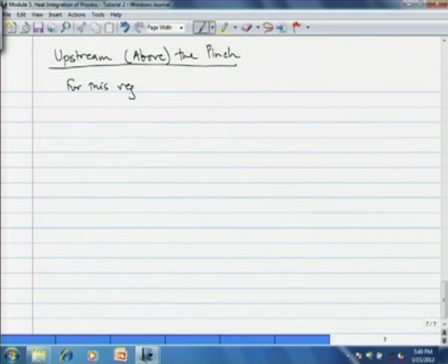In addition, for the above pinch region, we have some constraints as we have seen in the theory lecture. The constraints are: Cph has to be lesser than or equal to Cpc, and the number of hot streams has to be lesser than or equal to the number of cold streams. Now, let us see the heat surplus and heat requirement.